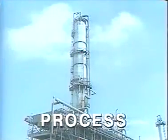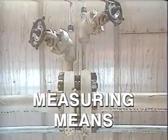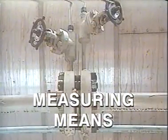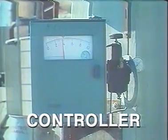In any control situation, whether the equipment is a process furnace or a home heating furnace, there are 4 things that are necessary. First, there is a process that needs measurement and control. For each process variable that must be controlled, there is a measuring means, one or more instruments that can measure the process variable. There must be some kind of control mechanism to receive the measurement information and determine how it compares with the desired value or set of values.